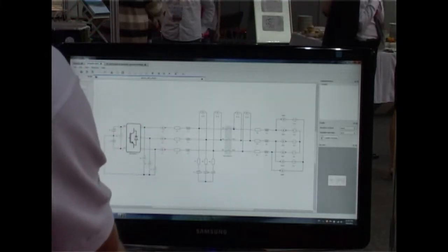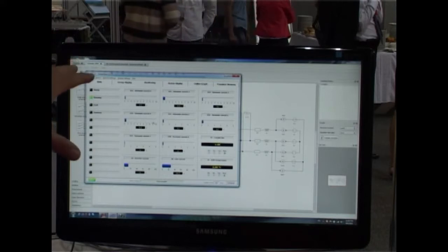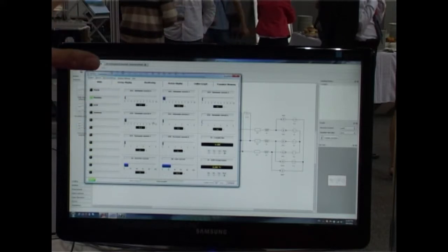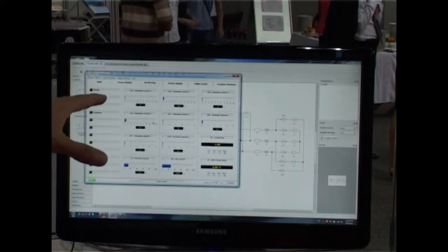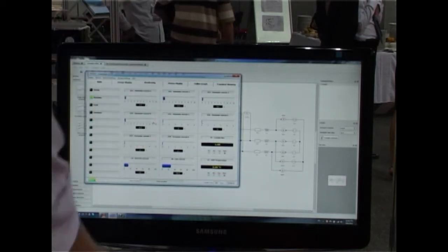But as we can see, the higher harmonics have much lower amplitude than in the first case, and the current going to the grid looks more like a sine wave. It was something that we really wanted to achieve with this application.